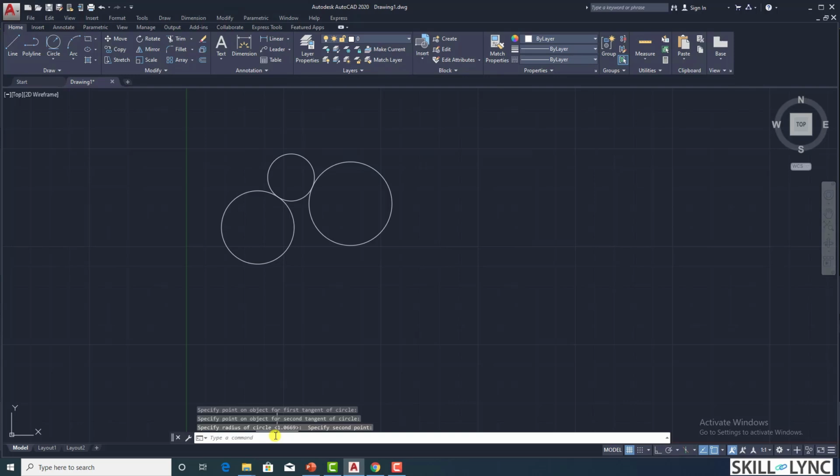So a very good user of AutoCAD relies only on the command prompt window to perform almost all of his operations. So for each and every command that you work on, try and look into the command prompt interaction so that you can repeatedly use it and take it to your benefit.